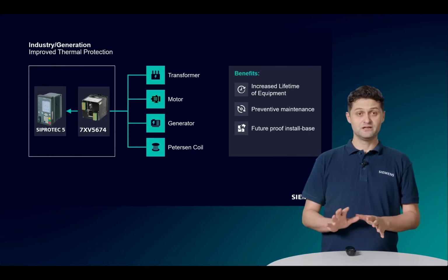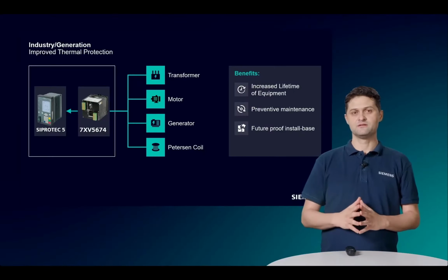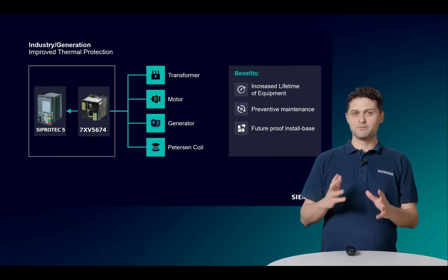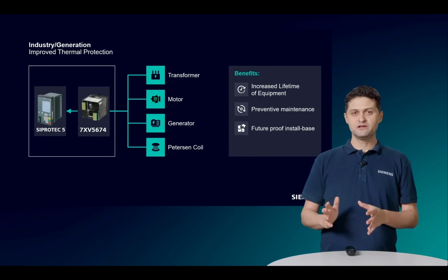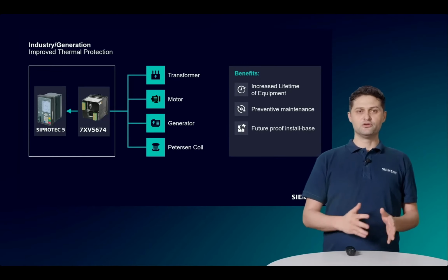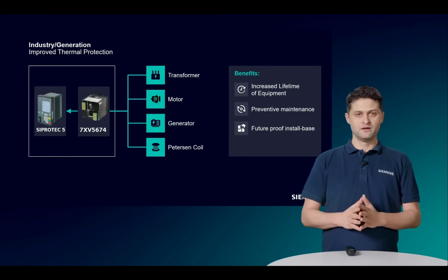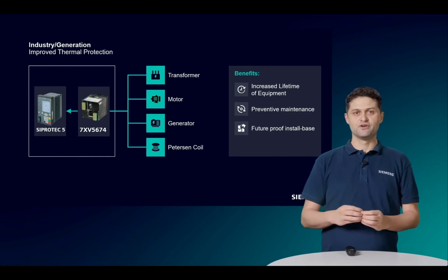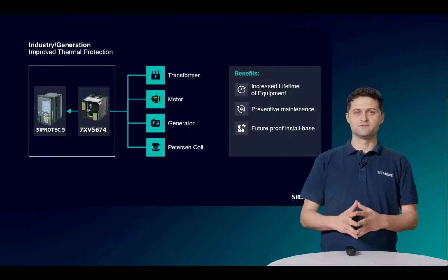But thermal modeling, only based on the current measurement, does not always lead to most accurate results, simply because there might be harmonics involved in the current, which is filtered down in the normal modeling, or environmental conditions may vary during the day. Sometimes after the long run times of the machine, thermal characteristics also alter. To make best out of thermal protection, an actual measurement is necessary to remove the environmental dynamics from the equations and have direct measurements of the temperature. This is where the Modbus client functionality comes into the picture.